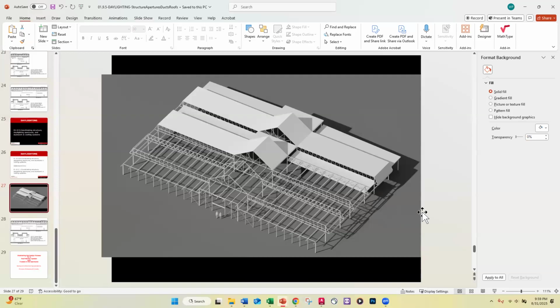Now, we subsequently made some adjustments to this concept. You'll notice in this case, there were beams running between these trusses, and that might in fact be the way all this would be done in the end anyway. But there is a simpler version of this, which says that the corrugated decking can run from beam to beam, or excuse me, from truss to truss if that corrugation is deep enough.